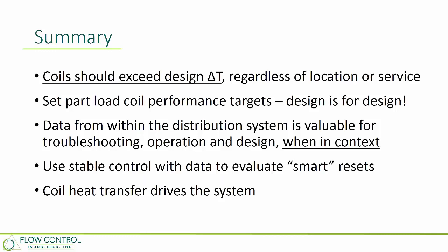If we look at anything else in a central plant, if we look at a chiller, you would never take that chiller operating kW per ton at design and use that as your expectation for the total, IPLV or total seasonal efficiency, right? We have a chiller part load curve, or a part load efficiency curve. We have part load expectations for pump variable frequency drives. We never take that peak load performance and say that this is the only variable that we have, this is our only metric, right?